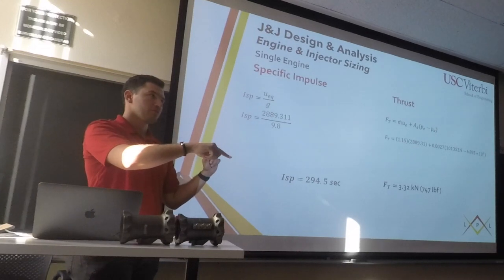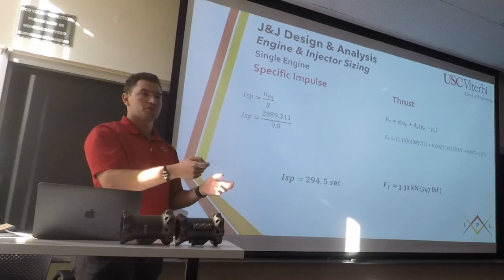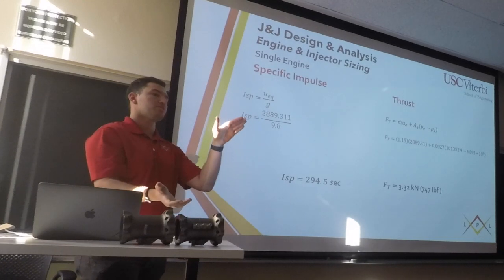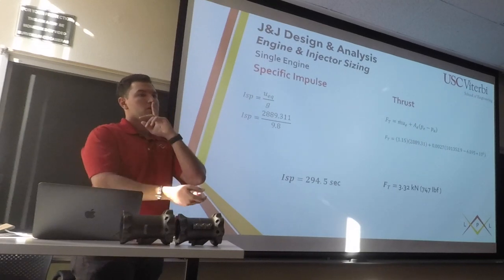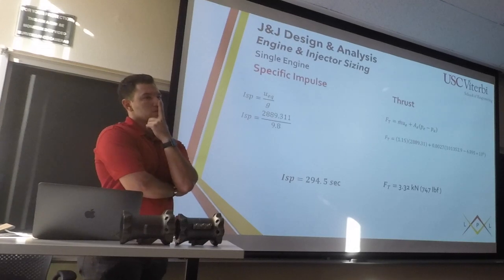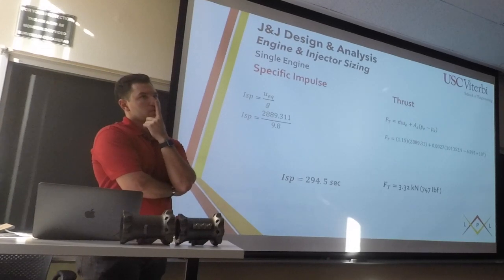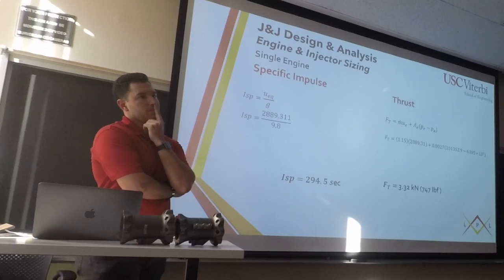it's the other way around. Does anyone remember? I always get confused with this. The overexpanded, underexpanded: one generates a shock at the exit, and one generates an expansion fan. Overexpansion causes the shock wave, and the under expansion causes expansion wave, I think. Yeah, I think it is. The Mach disk, the Mach diamond is caused by shock waves. Yeah, that's overexpansion.